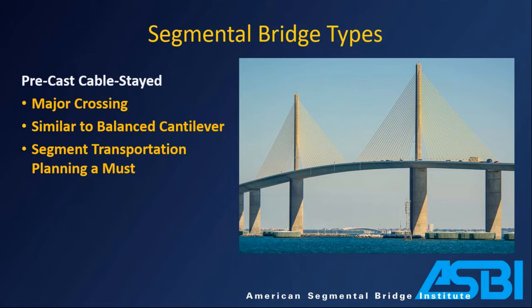Again, segment transportation and planning the moving and erecting of the segments is an absolute must. How are you going to get them there? How are you going to lift them? How are you going to deliver them? Are the stays going to be in the way? If you're trying to deliver them over the deck, do I have access to pick them from the water? Those are certainly things you need to think through as you work on a concept like this.